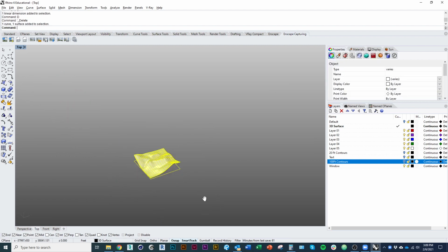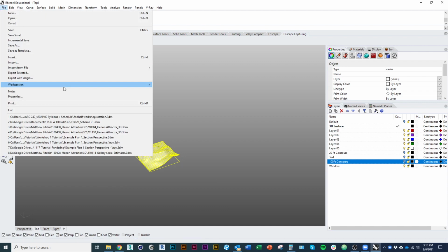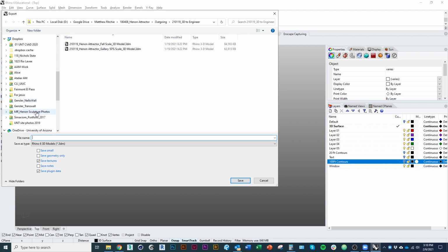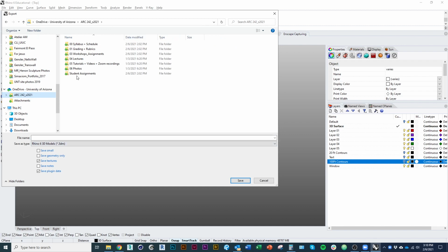Okay, great. Now, I actually find it useful at this point to transition to a different file, or transition into inches, because most of what we'll do from this point on will be in inches. So I'm actually going to export this file into another Rhino file so I can start to work on it in inches. In order to do that, I'll just select the objects there. I'll go to File, Export Selected, and then I can save that file. I'm just going to save it as a Rhino 6, and I'll just call that my scale topography.